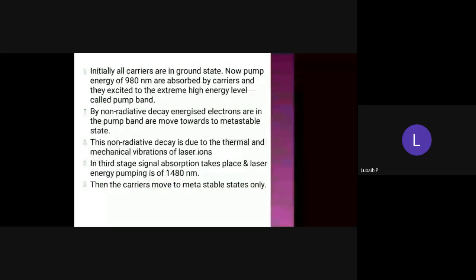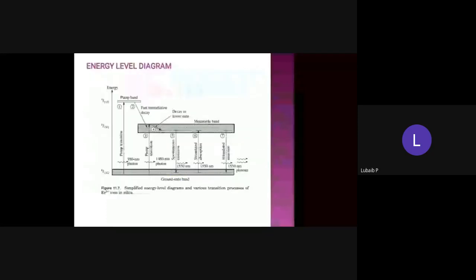And by non-radiative decay, energized electrons in the pump band move towards the metastable state. So immediately after these carriers are excited to the pump band by absorbing the 980 nanometer energy, they are at position one in the pump band.